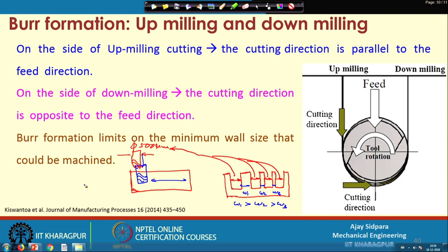Now, if you see from the vertical direction, this is your cutting tool, and the cutting tool will be rotating in this direction. This is your rotation direction, and now consider this is your workpiece. Then you will encounter two different types of forces. This is the normal force and this is the tangential force. So, this force is Fn, right, and because of these two different forces you will get material removal rate from the surface. So, now in the first cut you will most probably not encounter any type of problems,